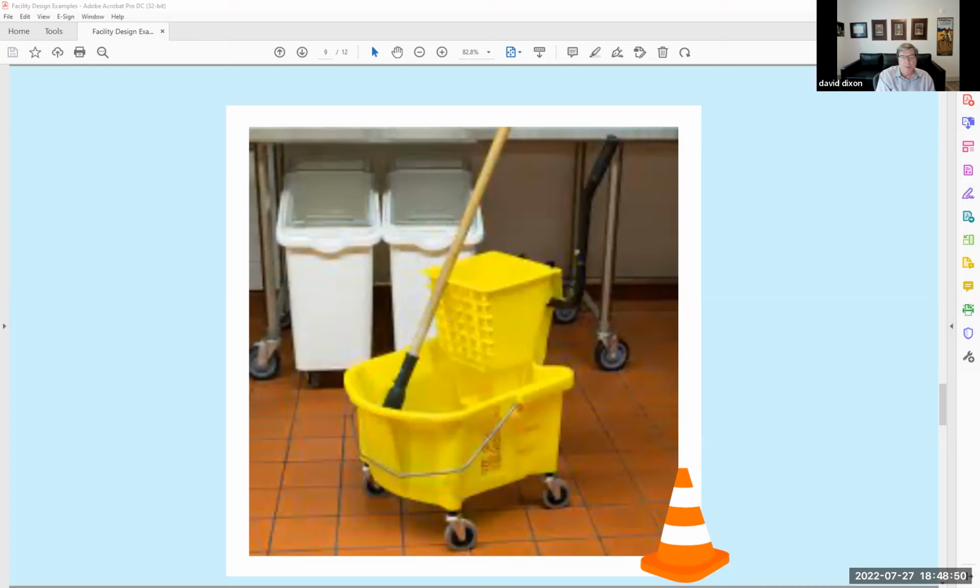But there are all sorts of details in a kitchen design that create microbiological harborages: things you can't see, things you can't swab, things you can't sanitize and verify that the sanitation step worked. Kitchen designs don't cut it. So you need to pay attention to this shift from a kitchen mentality to a manufacturing mentality.